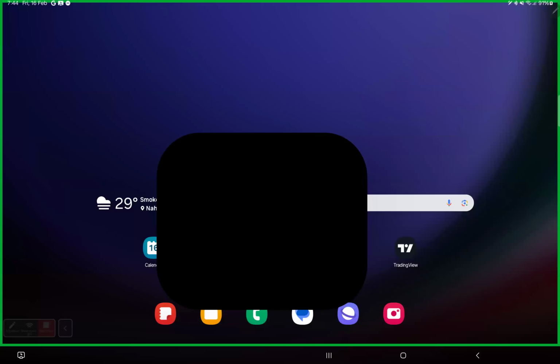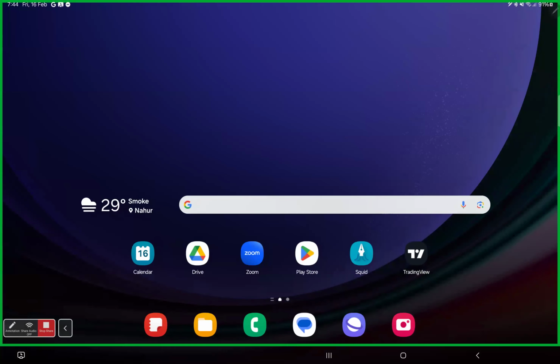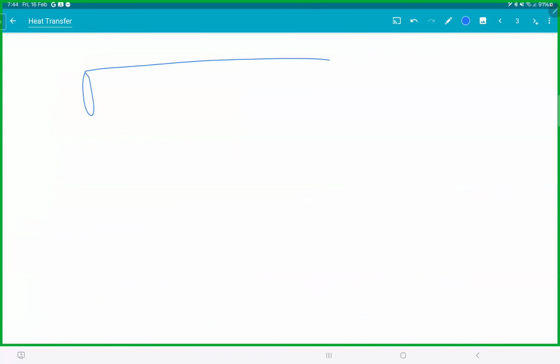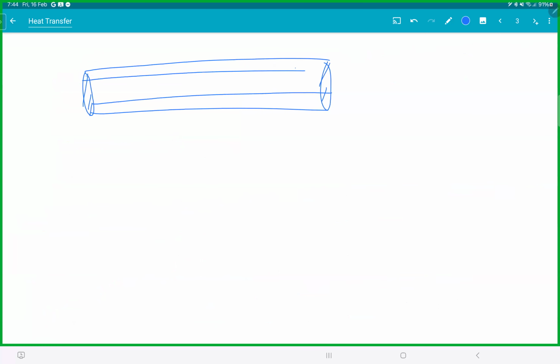So they're actually using convection in that. Let me tell you how it works. Normally in industries, we use heat pipes for fast heat transfer. So what happens in that? You have a pipe there. This is sealed and this is sealed. It's a vacuum inside. You have a small water drop here, and everything else is almost vacuum.